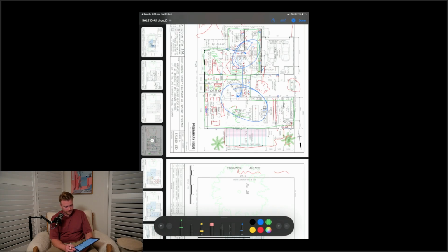And then the upstairs we'll probably just do a 7 kilowatt and run it independently. So they're all thermostatically controlled. There's no baffle boxes. It's all just individual units. And having 3 units, it sounds like it would be more expensive, but the outlay of the units is probably a little bit dearer in terms of, instead of having a big 21 kilowatt 3-phase unit, we've got a 7 kilowatt single phase, 10 kilowatt single phase, and then a 14 kilowatt 3-phase. So we're able to sort of balance loads a bit. And we're sort of able to control it.